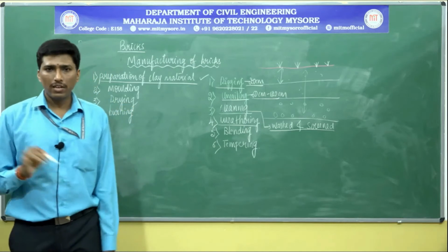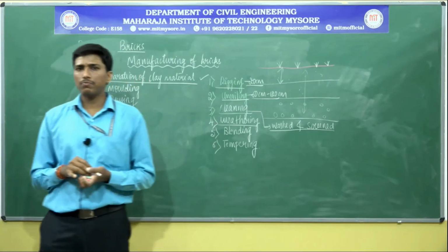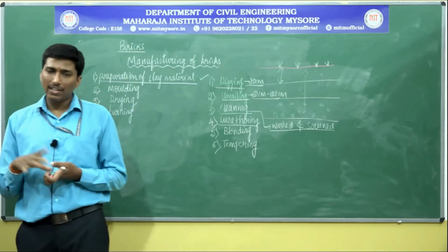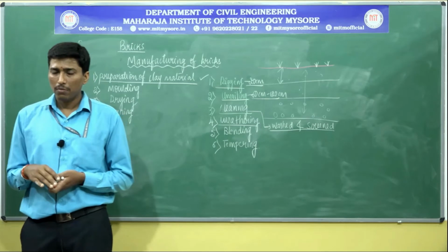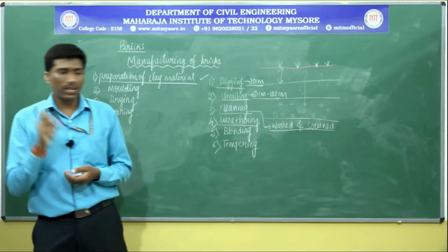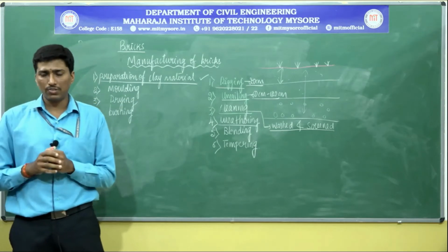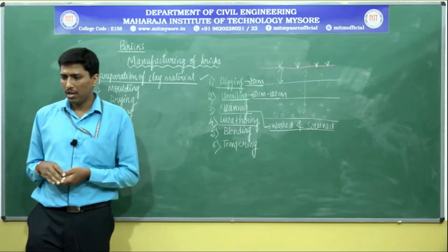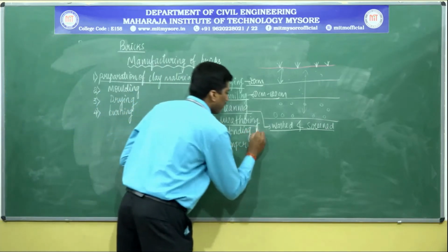These diurnal variations takes place. The weathering is subjected to make the clay harden in nature, because though it will be soft in nature, it has to be rendered to some proper degree of the hardness. That has to be taken up. We call it as a softening or mellowing, this weathering phenomenon.